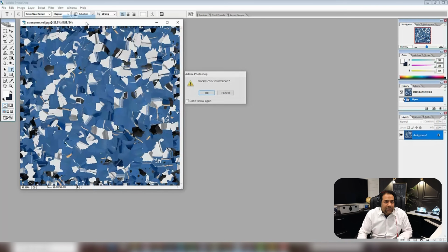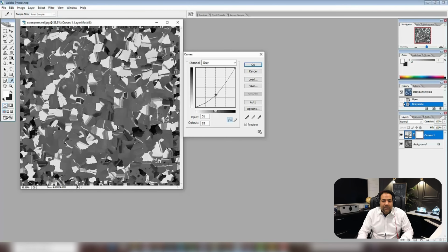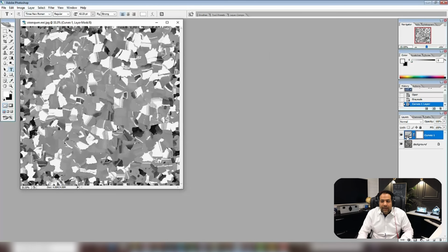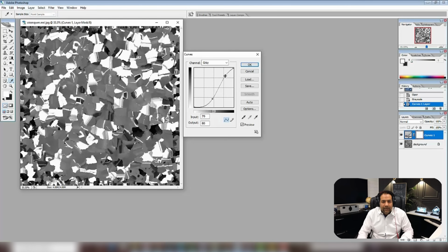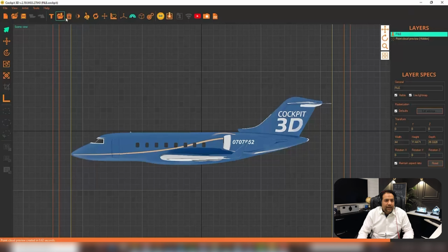And yes, I do know that the texture looks different, but it's because it's a texture wrap for 360. So essentially, this process requires an OBJ that is under 100 megabytes and one single texture graphic file. That's it, okay? Not multiple graphic files, just one that has everything wrapped into it. And what I'm doing here is I'm just brightening it. I'm gonna apply an S-curve actually, which does brightness and contrast. Merge it, save it, Control S, and let's refresh it.